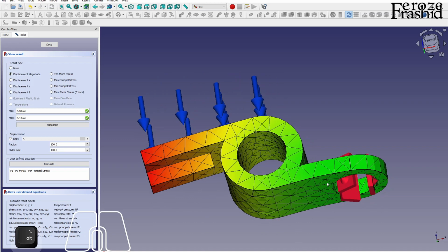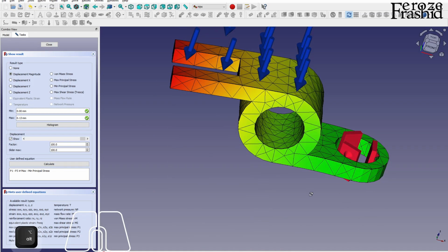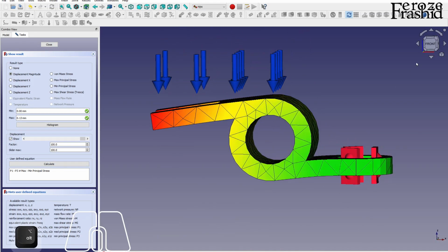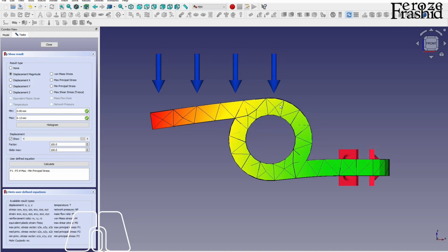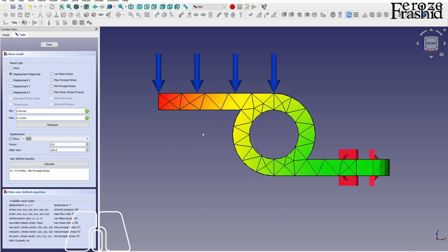Had I made this surface fixed, we would not have any displacement in there, but the way our support system works now, there will be a little displacement in here. This circular portion did not show much deflection itself, so the whole thing is moving, but it's not displacing this entire circular shape. So the circular shape is not becoming oval shape.